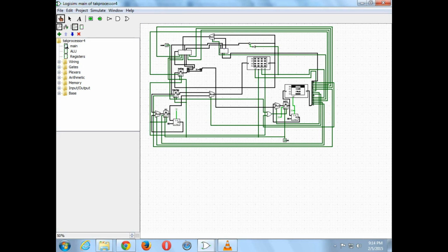So there is software out there that can take the output of this file, which is just an XML file, and convert all the gates to very low level gates, like NAND gates and stuff like that. You can then take that specification file and load that content into one of two different chips. One type of chip is called a CPLD, and the other is called an FPGA.